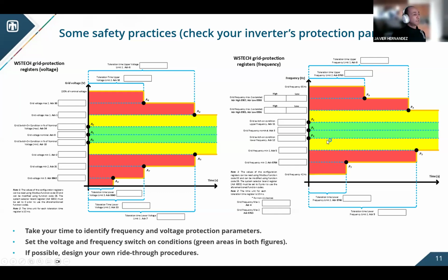And if possible, try to design your own ride-through procedures, okay? And verify them, validate them. So you are certain that you have your equipment very well protected against instability or overcurrent or undervoltage scenarios that we really don't want during stable conditions.